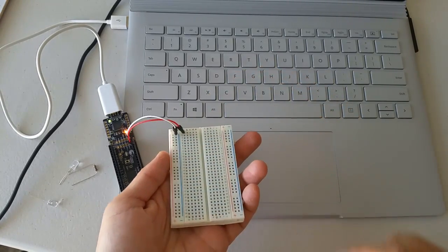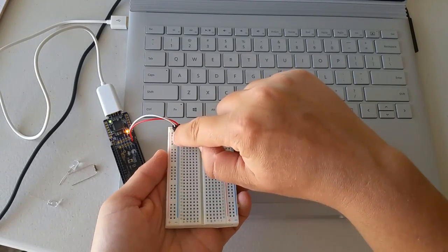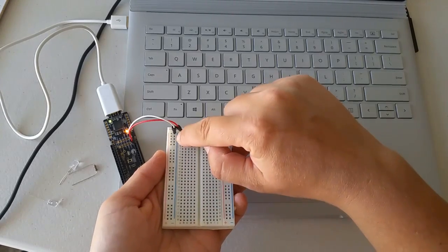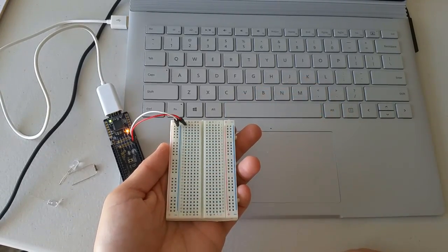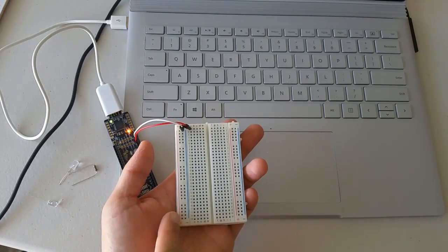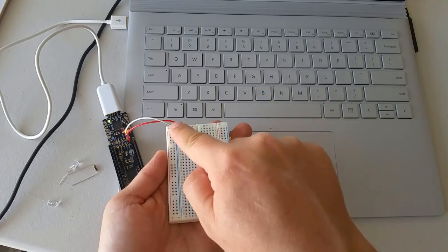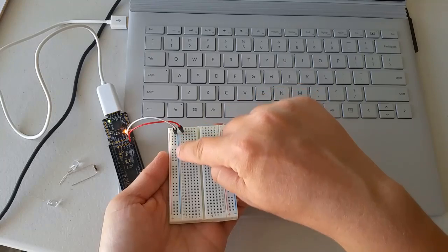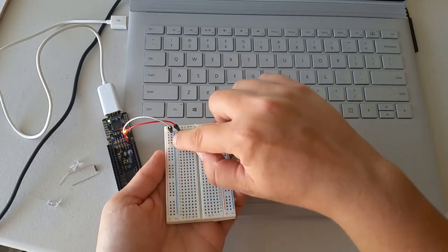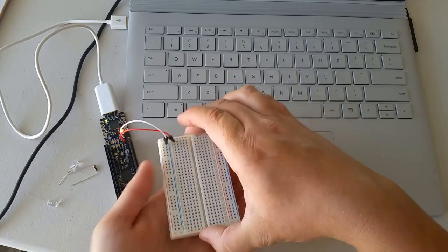On the left-hand side and the right-hand side of this solderless breadboard, one of the columns has a red stripe next to it, and one of the columns has a blue stripe next to it. Oftentimes, we will use the red stripe to be power and the blue stripe to be ground. So by using a jumper wire to connect one of the pins in the blue stripe column to ground, we'll make all of the pins in this whole column all connected to ground.